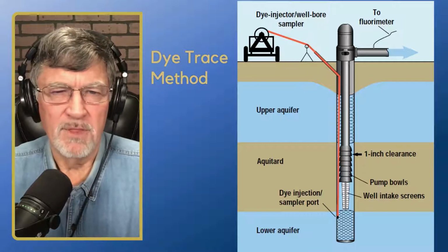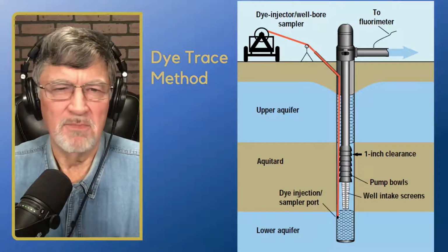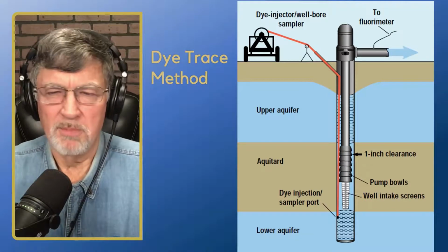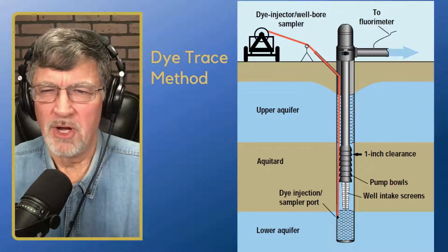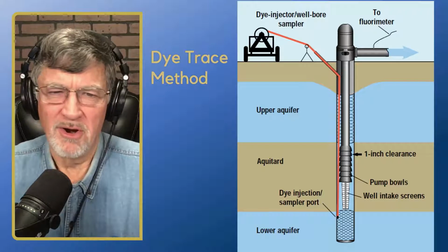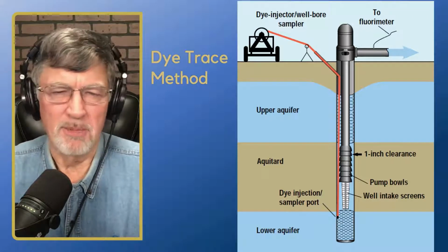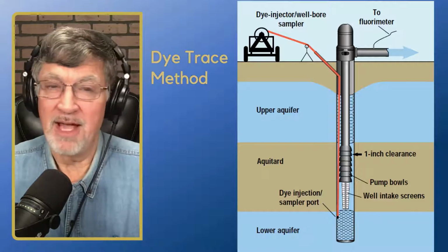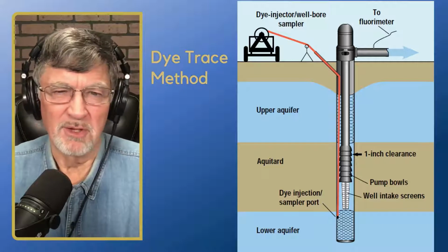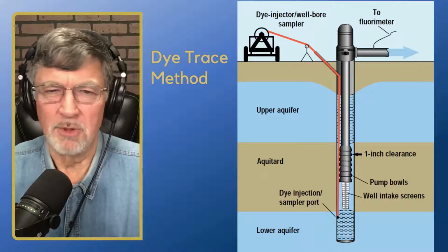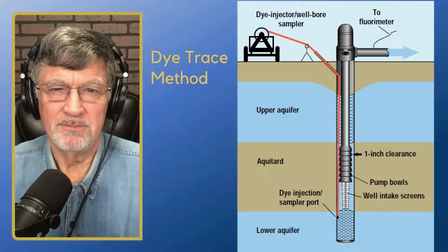And the big promotion on this is that you can install these things and run it with a pump in the well. That's not always true. We see a lot of wells where the pump bowls are so tight that you can't thread down past them, and so you've got to pull the pump anyway. And that happens in a lot of cases. So my experience is, generally 50% or less of the time you can get down there without pulling the pump. But where it does work, it works pretty well in that regard.